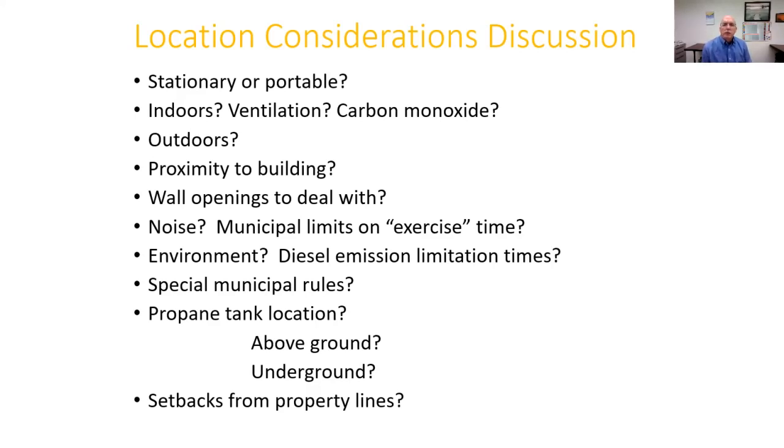So outdoors, where do we put it? How close to the building? What wall openings do we have to deal with? What about noise? Are there municipal limits on the exercise time and how much noise these units can make? What about the environment? Are there diesel emission limitation times? Are there special municipal rules in your area? How about a propane tank? Where are you going to put it? You want to use propane tanks instead of natural gas? Are you going to put them above ground, underground? Do we have setbacks from the property line?